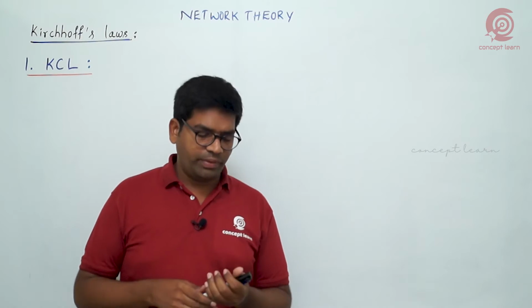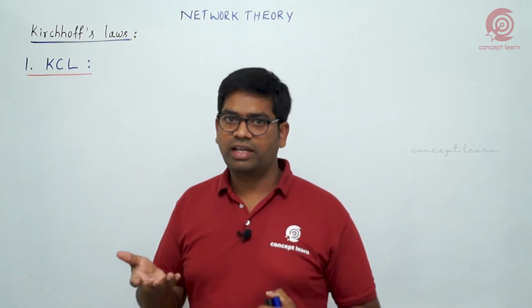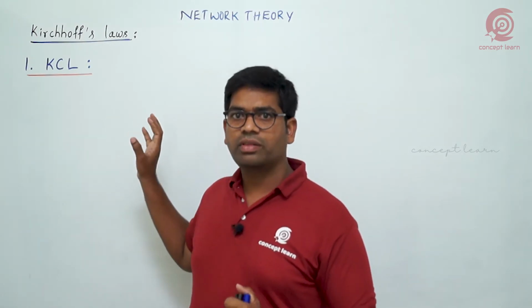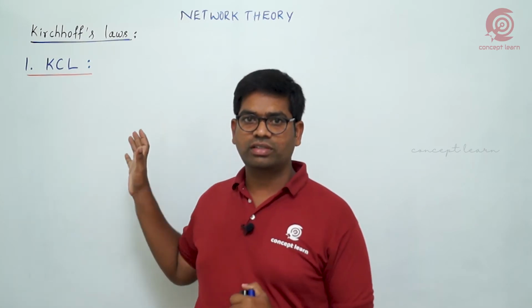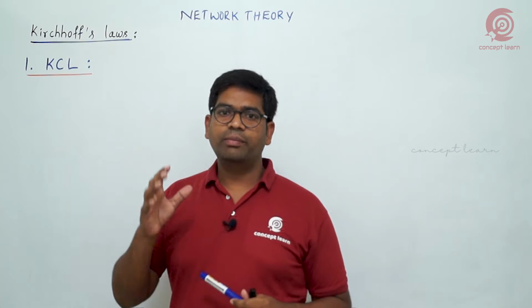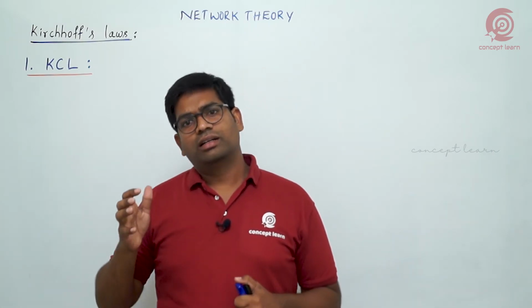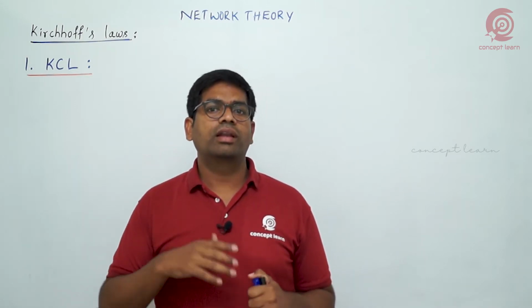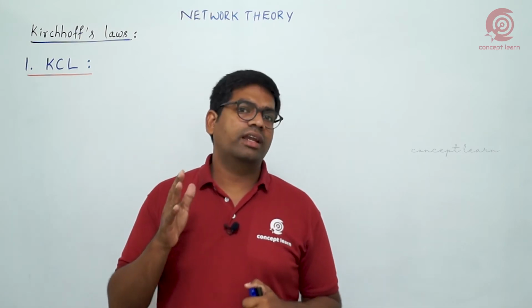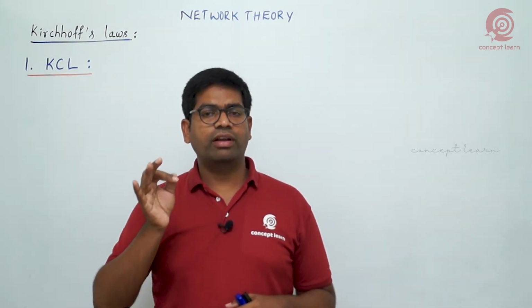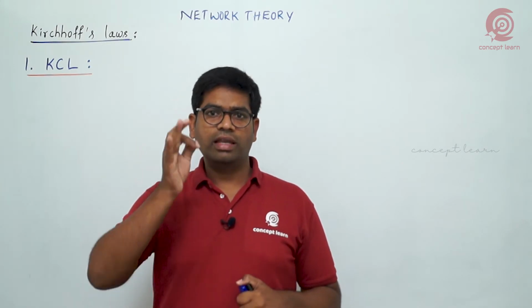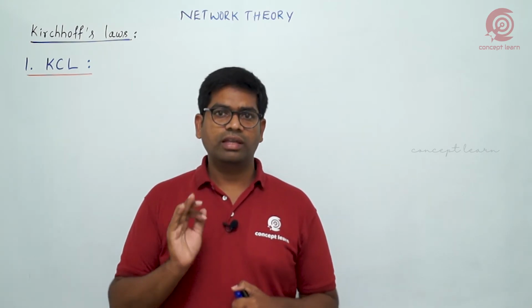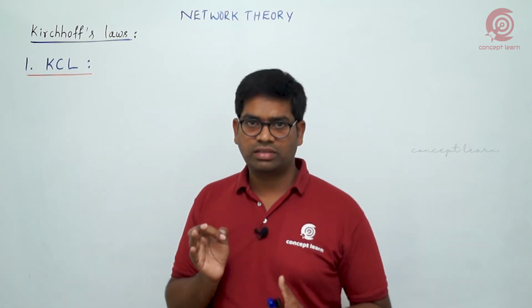Now the statement. Here I am explaining the statement, and we will write it on the board also. Then we'll take a sample example and see how we write it. That is the objective for this KCL. Generally both KCL as well as KVL we write only for lumped circuits or lumped networks. So how do we write the statement here? In any lumped network, for any of its node, the algebraic sum of leaving currents is 0. It is a basic, conventional statement.